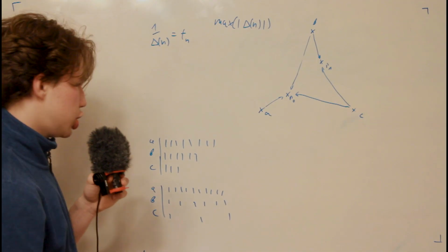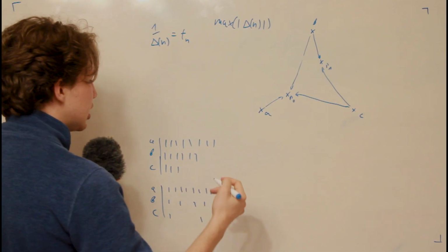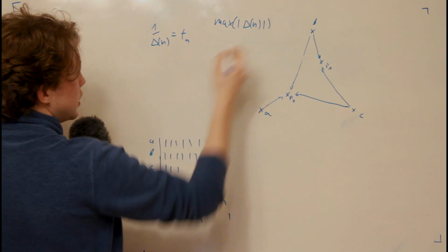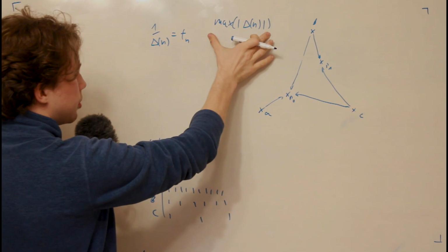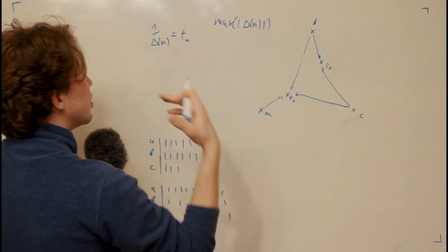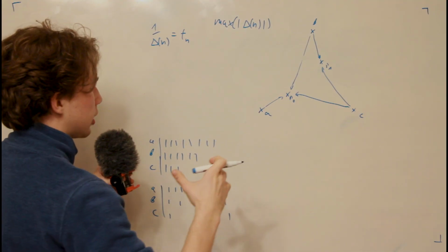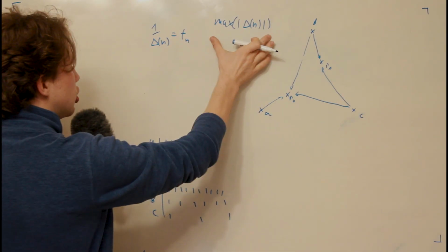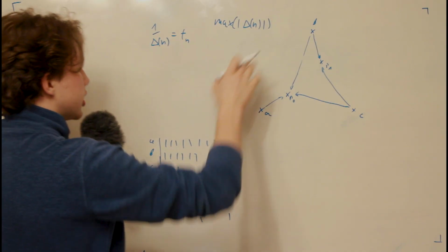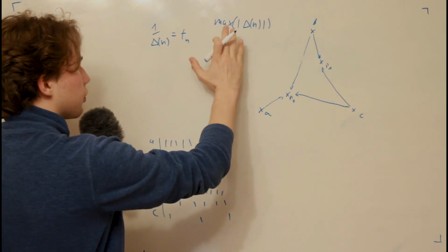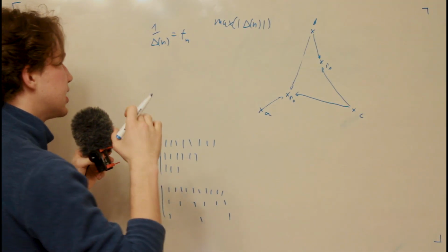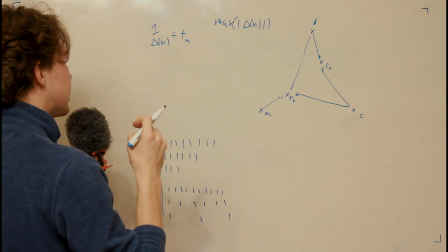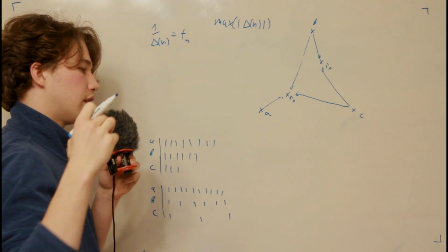So how do we achieve this? We achieve this by taking the basic coefficients. First of all, we need to find the one with the maximum run, the one that needs the most distance. This is going to be our key value. We're going to orient all our timing of the other motors based on this one motor. And with that, we are going to calculate the coefficients.